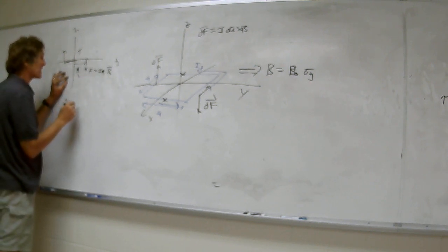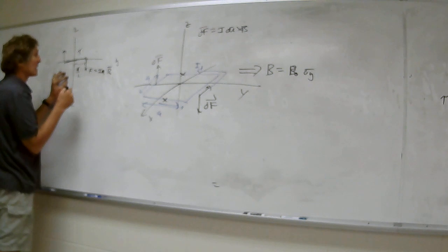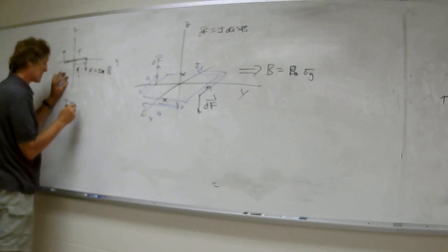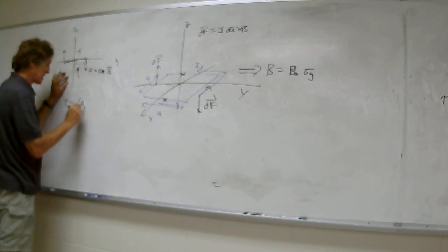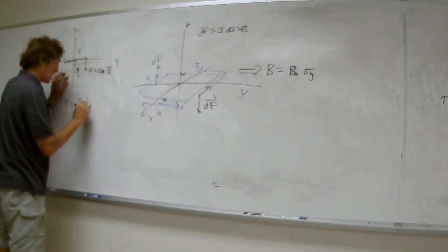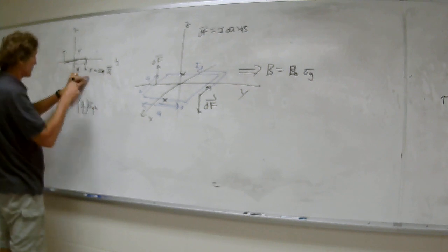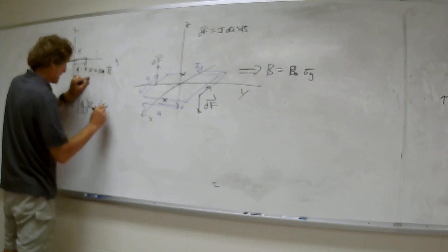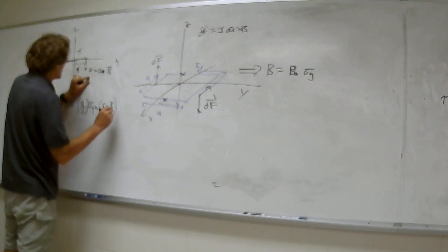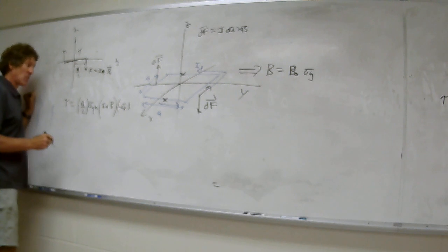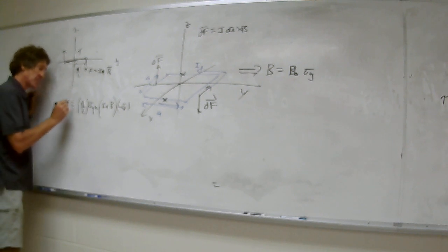So it's really simply equal to this vector direction. I'll just write it down so you can see it. It's going to be A over 2, and I have that in the y direction, AY, crossed into the force downwards, so it's going to be IA times the B field, in the minus AZ direction. That would be the torque from 1, and since there's 2, it's times 2.